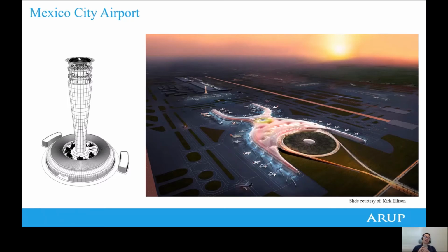The geological condition of Mexico City is very complicated, and I will not pretend to be an expert on that, but due to the special content of Mexico City clay, as well as possible basin effects, the ground motion at the surface is usually amplified significantly, with a very large site period.